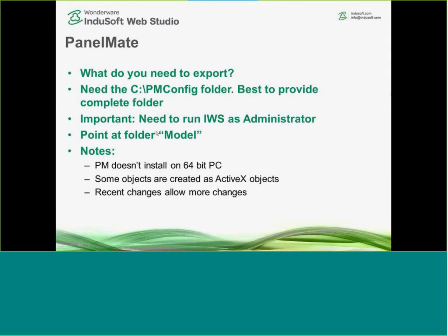Now, when you convert these projects, some of the objects, we didn't have exact matching objects, so we created some special ActiveX objects. So some of the objects are not brought in as native InduSoft objects, they are brought in as ActiveX objects. And recent changes that we've provided to this tool, very recent changes, allow you to do more editing. For example, if some of the objects were included in an ActiveX object, you couldn't ungroup it.